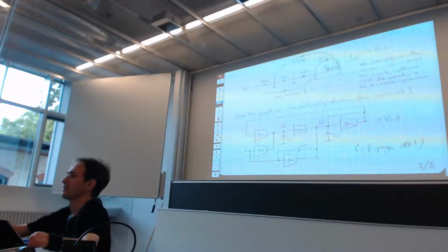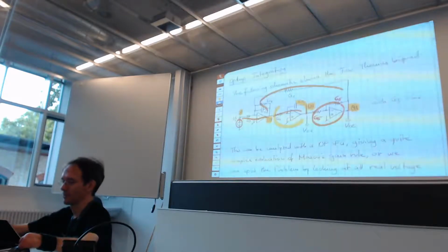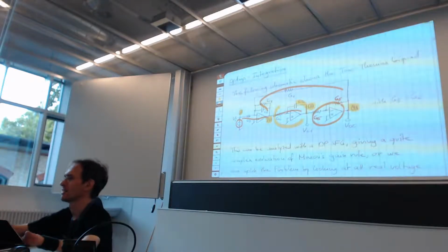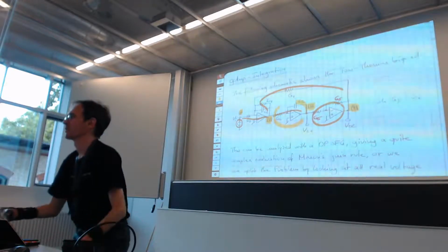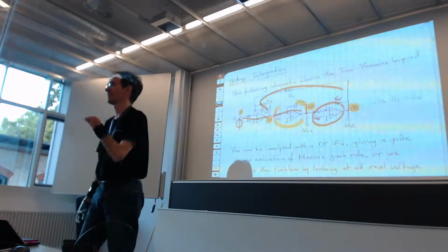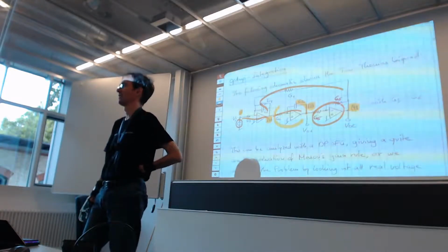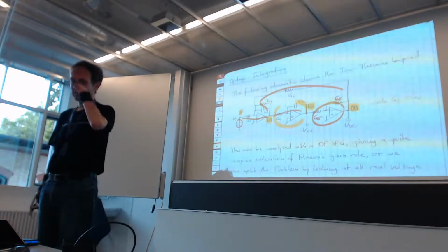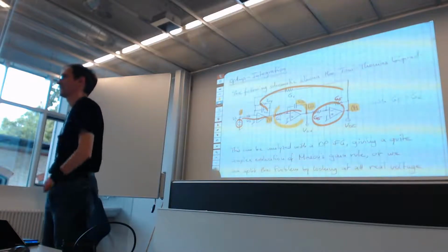Even if it is audio, you can tolerate quite a lot of distortion, if not disturbance, but distortion in audio. But if this is something where distortion is a problem, so very high linearity audio or so, then there is no way around doing something like this where you actually have very good feedback, to keep the distortion low. But these are again second order effects, you see. So this is only worth thinking about if linearity is an issue.